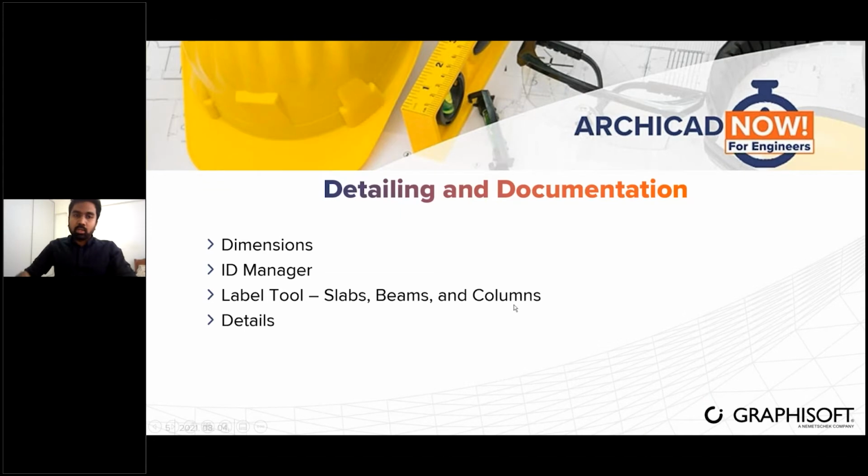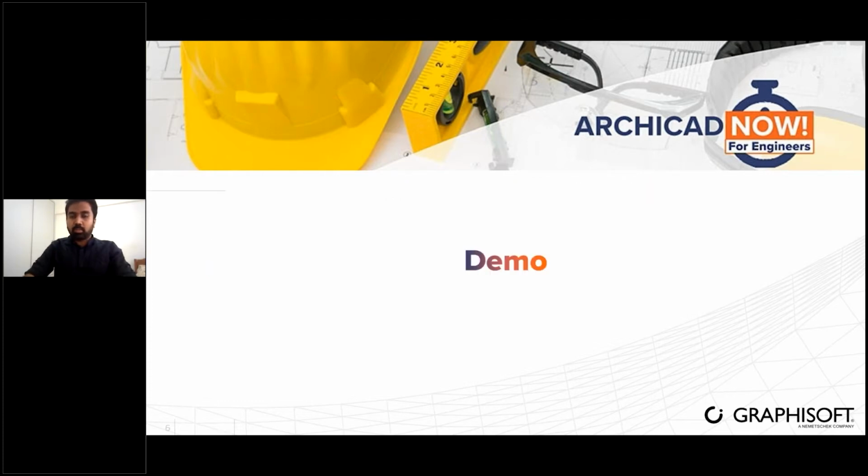For today, we are going to continue with the detailing and documentation for our structural BIM model, which we prepared in the previous sessions. We are going to do the dimensioning for it on the GA plans, and we are going to use the ID manager to assign unique IDs for different components. Then we are going to use the label tools to mark the IDs of components and their dimensions. And finally, we'll create details using two different methods, which I'll show you during the demo.